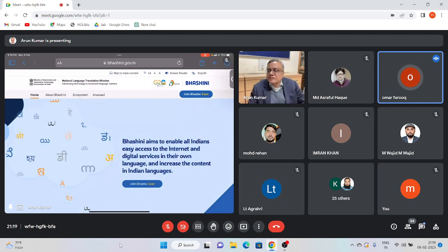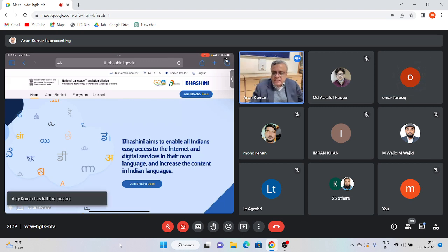Thank you. The next question is by Ms. Rohan Nessa. The question is, is there any optimum choice for window duration to be employed for speech processing applications? So we have two parts. One is the excitation part, which is basically creating the source signal, which is input to the vocal tract. Now, the excitation signal varies at a faster rate than the vocal tract resonances.